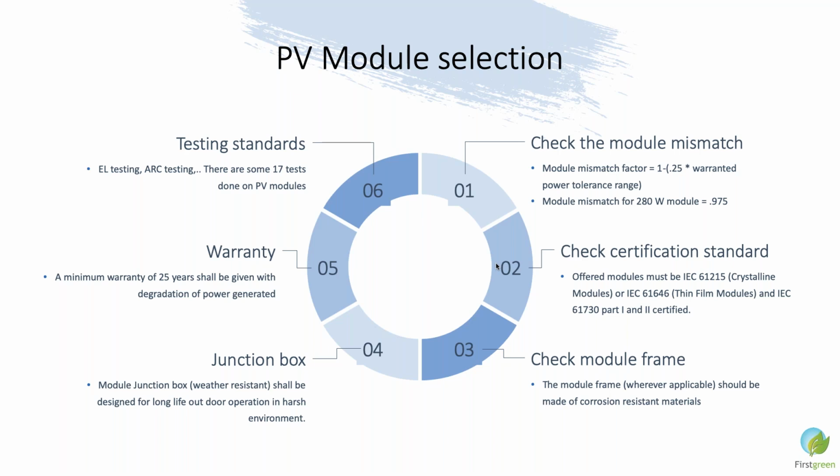The junction box is also equally important. You can mention all these things as part of your purchase note, your module technical specification, or bill of material; there is a bill of material of the module also. So, what type of EVA coating, what type of steel for the frame, and how much the glass thickness is.